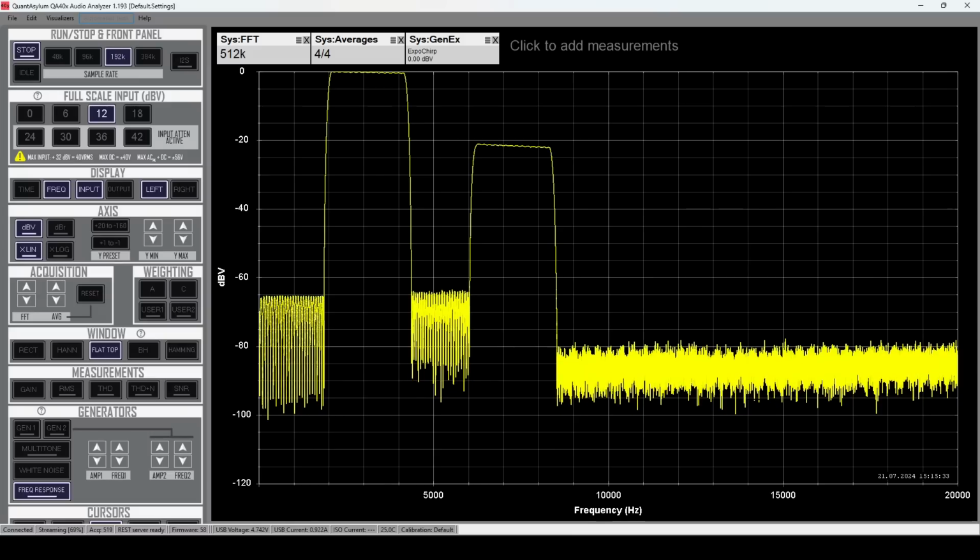And these FIR filters compared to IIR filters are comparatively very precise in the frequency bands they can attenuate, amplify, and so on. They don't suffer the same stability issues, but they do come at a price that they are rather expensive to compute. We are essentially computing convolutions, and doing this in real time, for example, in an audio system, can be quite time and computing intensive, even on these STM32 microcontrollers.